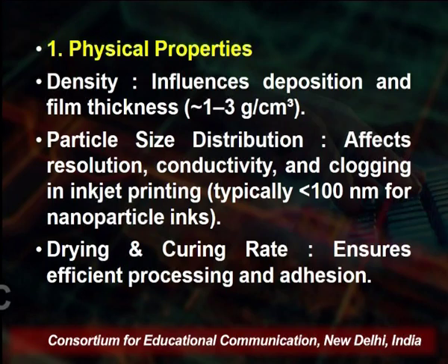Next is the particle size distribution, which is important because it is required for the resolution of the printed device. Particle size distribution affects the resolution, conductivity and clogging in inkjet printing, and the particle size must be greater than 100 nanometer for the nanoparticle inks, because we are preparing nano devices.